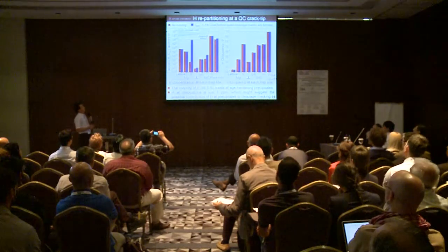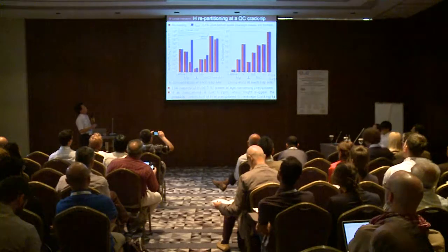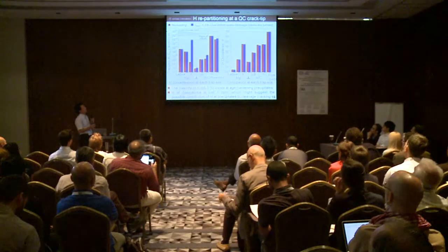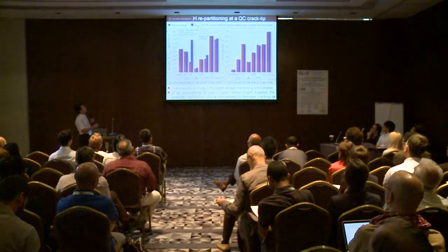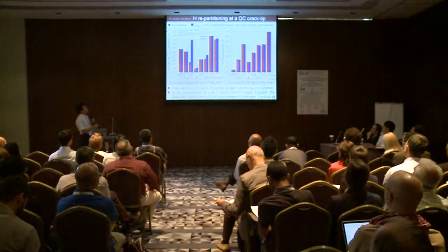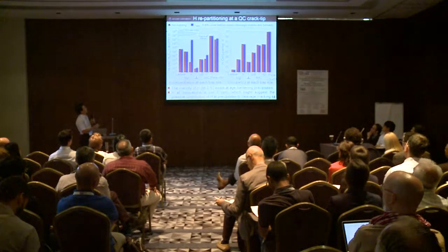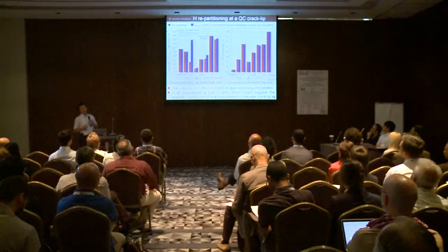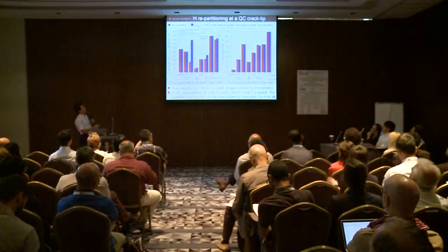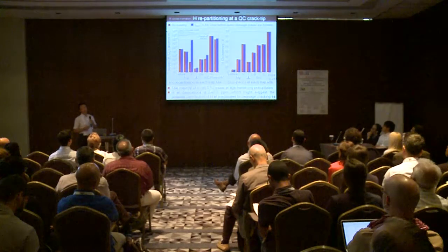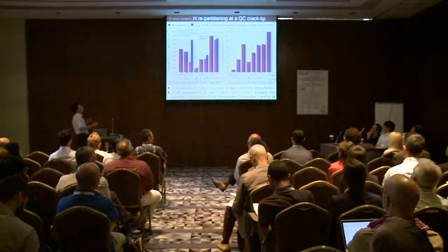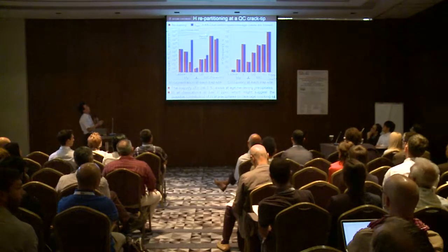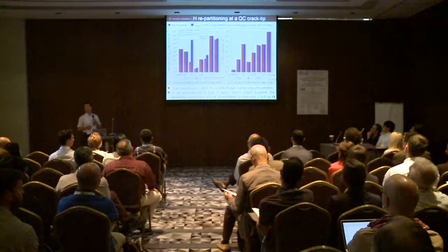So this is the very last slide. We are looking at very localized hydrogen partitioning, repartitioning during deformation at a quasi-cleavage crack tip. So what we do is at the applied strain of 4.4%, we have a crack here. This is quasi-cleavage crack. And at the next rolling step, the crack is extended to this extent as a form of quasi-cleavage cracking.